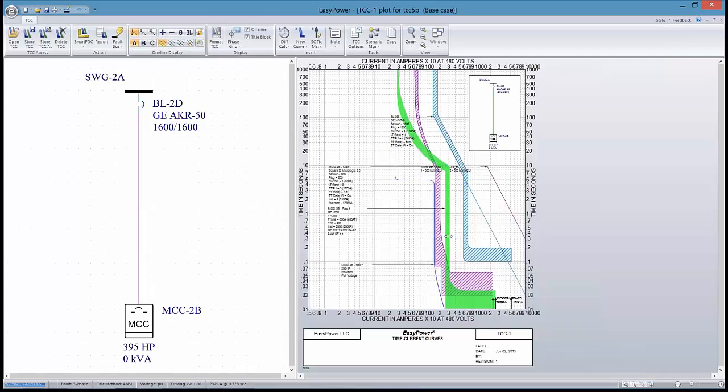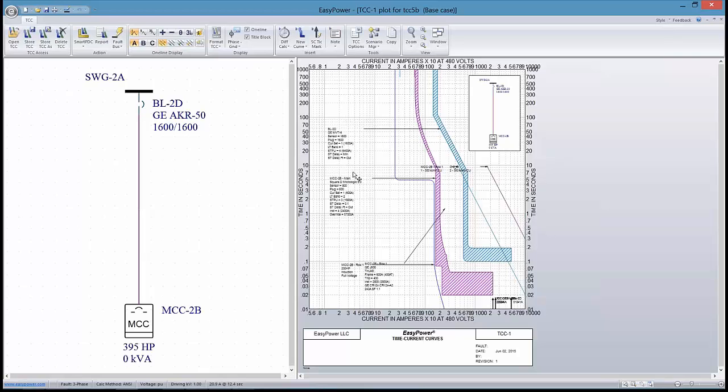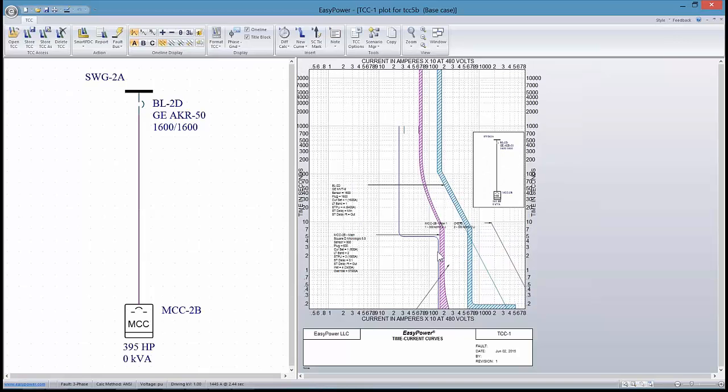It is important that this be set up where it is with respect to the motor start curve, and as long as we've confirmed that, we can take that off our plot. The next step that we're trying to deal with is to make sure that our main breaker is now coordinated with the upstream breaker, and it looks like the main breaker will not trip on a normal starting curve.